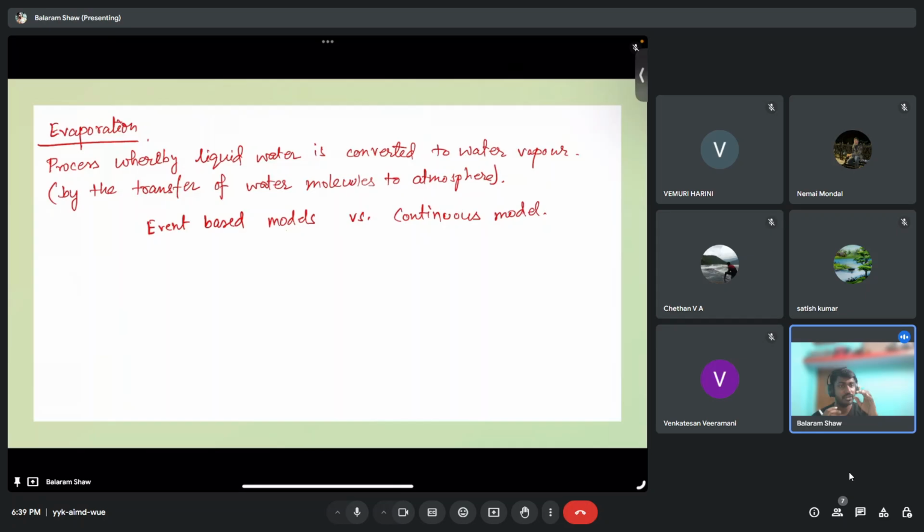Next, we have soluble salts. We know that if there are any impurities in the water, that will hamper the evaporation. So let's say if soluble salts or any impurities are there, it will reduce the evaporation, right? So we know why we put salt in boiling water and all. We are not going deep into that because we know this. Evaporation loss from saline water bodies, let's say sea or ocean, will be 2 to 3% less than that of fresh water, right?